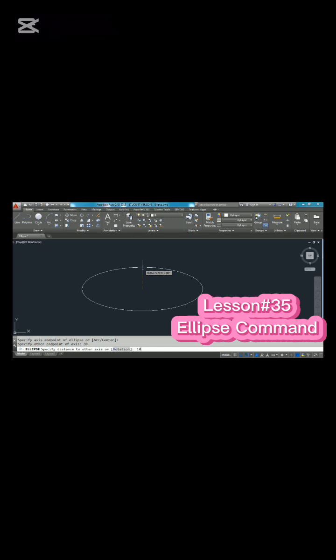Then type 10 at the command prompt and press enter. You can see an ellipse with 30 units horizontal axis length and 20 units, that is 10 means half of the length of the other axis, minor axis length we have given. So using those two dimensions an ellipse has been drawn.